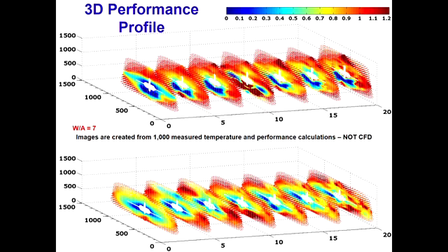This is the performance profile of this particular Westinghouse. So we take all that temperature data, we apply the HEI formula, and we can calculate per bay or per unit length the cleanliness factor for the individual tubes. And so again, if you take that yellow color that I talked about, the 75%, you can start to see the boundary of the airbound zone for these Westinghouse condensers.